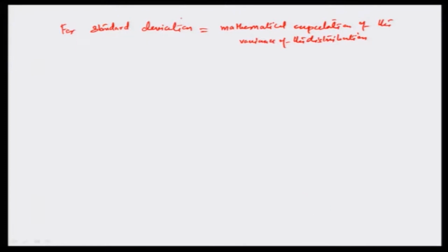When we are talking about variance, it is basically the square of the standard deviation, and we are talking about the variation or variance of a case where we have exactly r rejectables in a sample of size n with a fraction defective p. The sample, the drawing condition, the overall lot size does not really change in this particular case.